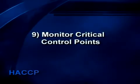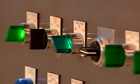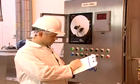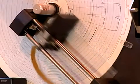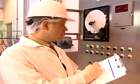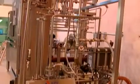And this is the 9th step to implementing HACCP. Monitor critical control points. Once your control measures are in place and food safety criteria has been established, decide on effective monitoring procedures. To ensure food safety, you must establish a monitoring schedule. Continuous monitoring using automated methods is best. Also, in some cases, regulations require continuous monitoring, such as using a chart recorder when pasteurizing milk.